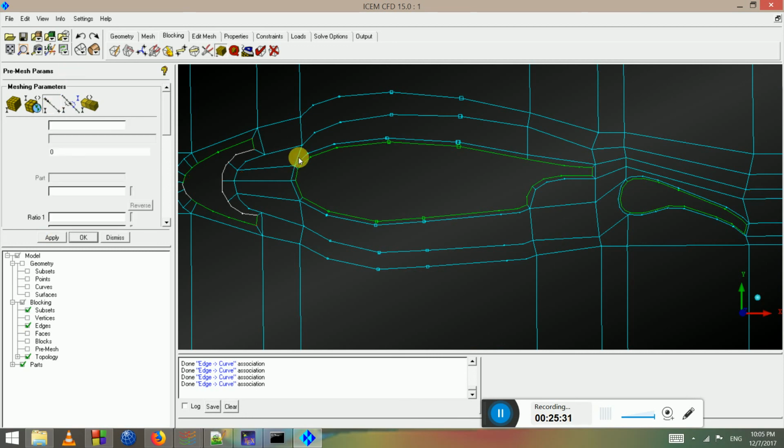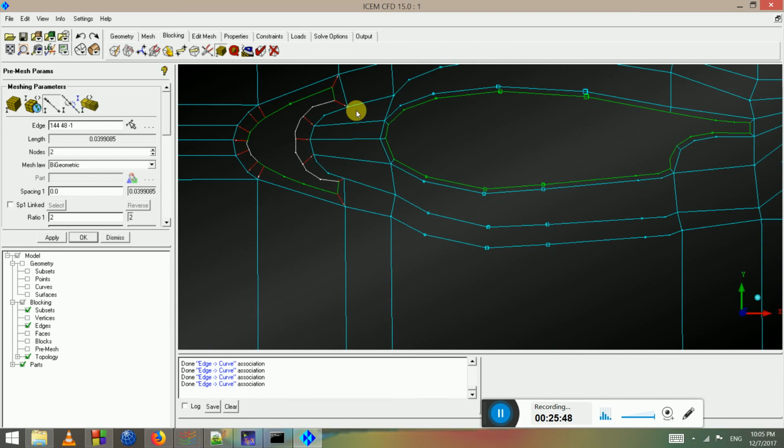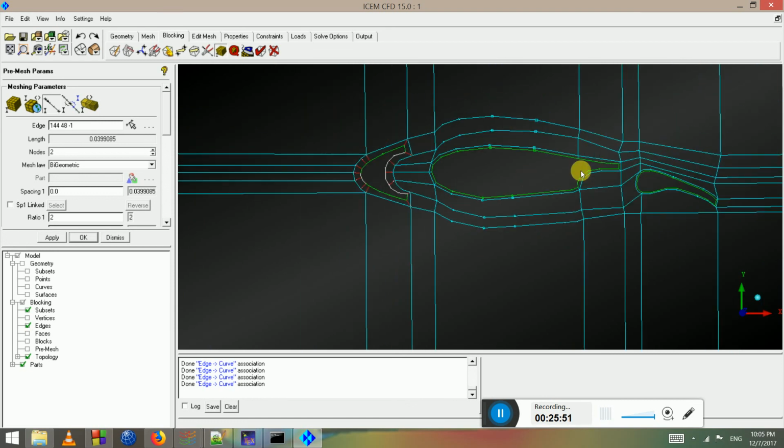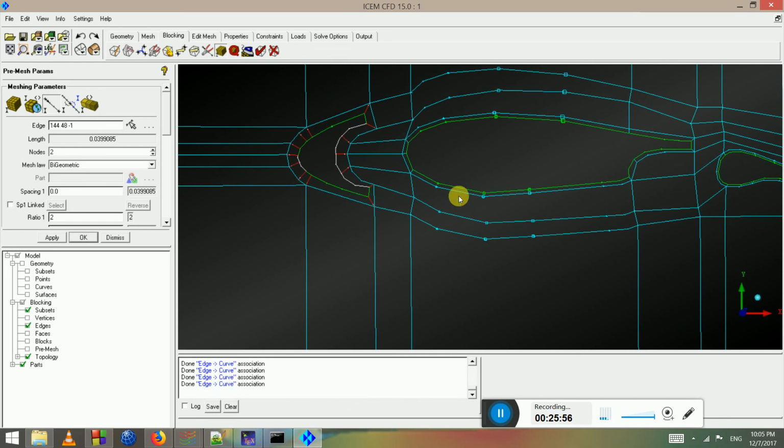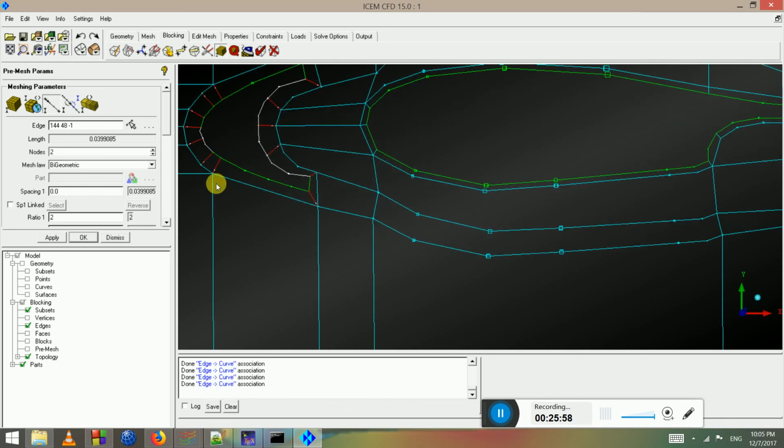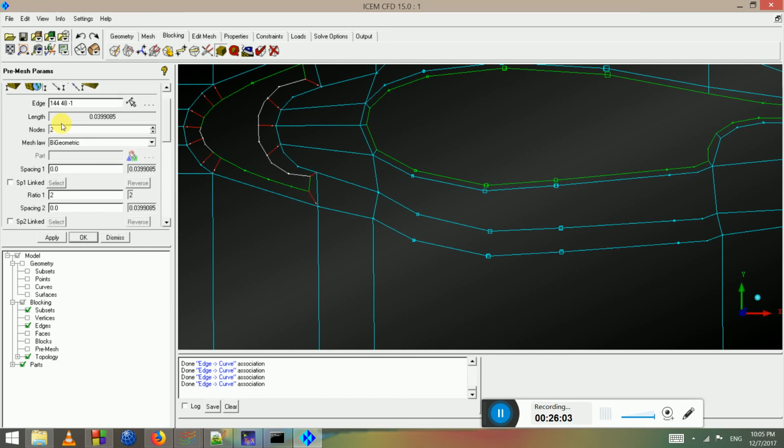And the O-grids. Now remember, I did O-grids separately for the 3 parts so that the spacing values can be controlled separately for the 3 parts, if you want to control it according to the local chord length. So I'm going to put 12 boundary layers and 1.1 and 0.001.